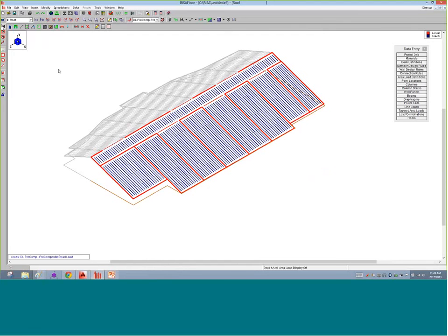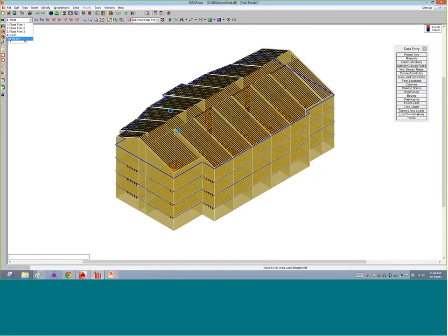So we've got everything laid out in the structure. We can go back to our full model, and we see here the entire structure is laid out. I'm going to go ahead and run this model, and as we run it, it's calculating the loads down the building. And so we're counting all of the gravity loads per floor level. So everything is going one by one, counting all the walls. If we had columns in this beam or posts, we would be counting all those post loads straight down the structure and doing all of that gravity design.